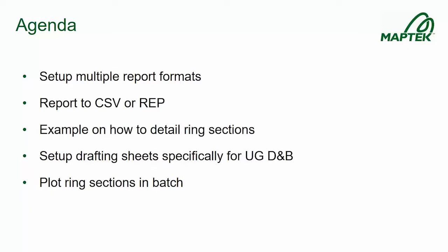We'll be detailing your ring sections for plotting, which is crucial for conveying the proper information to your drillers. I'll demonstrate polygonal outline section profiles of some of your triangulations, such as your stopes, ore contacts, drill room. We'll be labeling, doing some dimensioning on the ring sections. Then we'll take a look at the special drafting sheets.